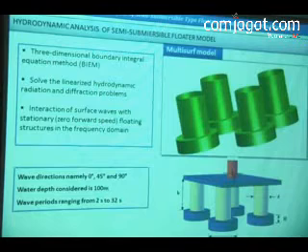That was based on experiments conducted previously, where people used WAMIT analysis for semi-submersibles, then did experiments in the wave tank, and found what amount of damping can be introduced in WAMIT to bring down the responses. The same concept was utilized here, and 4% damping was reasonable to bring down the huge responses produced by WAMIT.